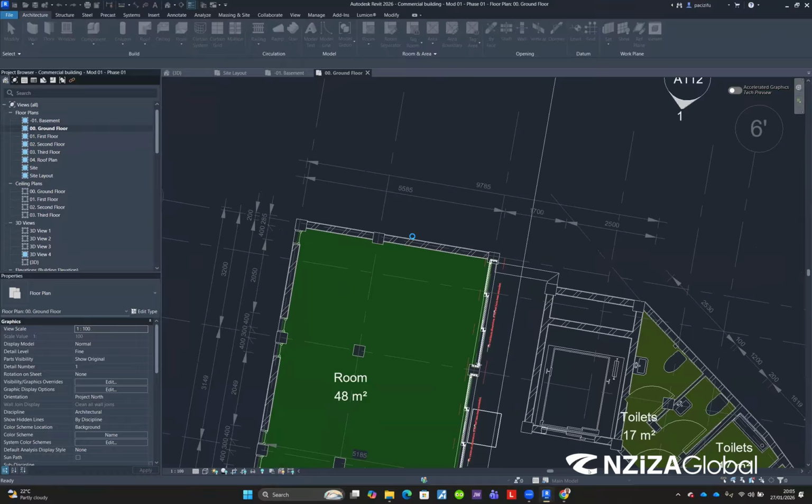But you will use New. If you don't have a file, you click on New. Then you will get this one for template. We have those metric templates, and we are using metric right now. But you can browse for another one here. You just change to metric, then open.